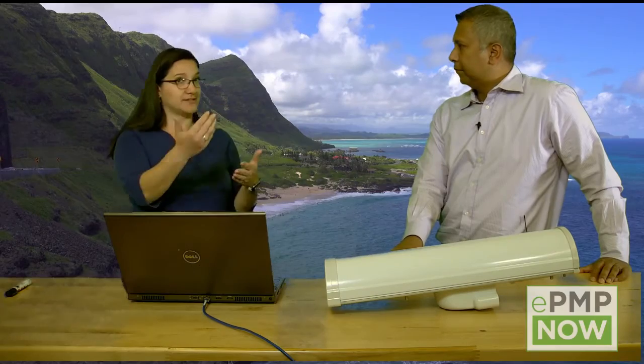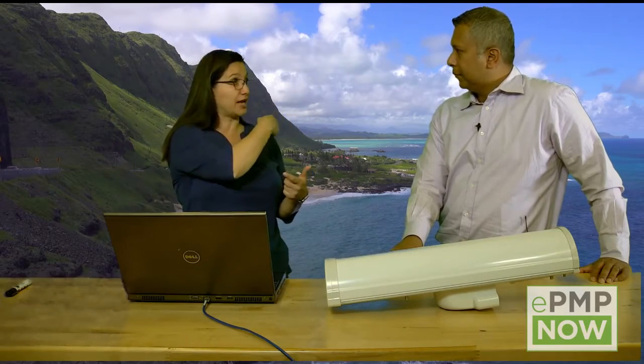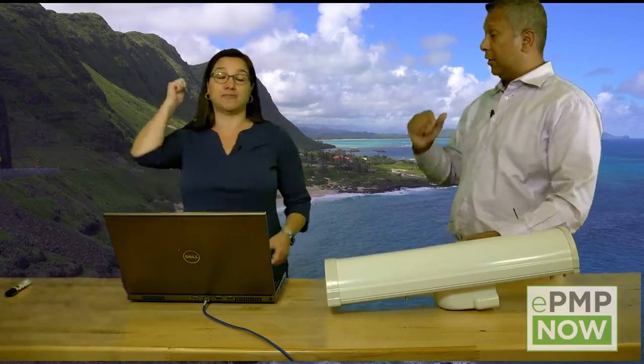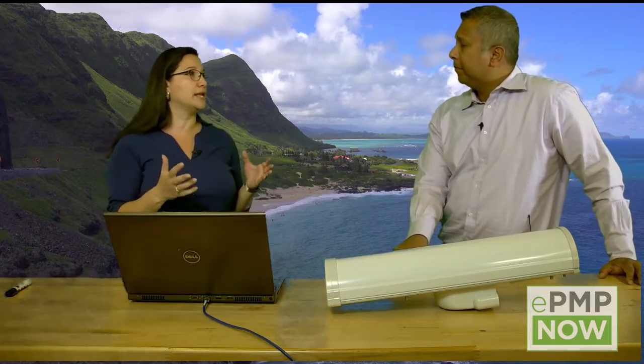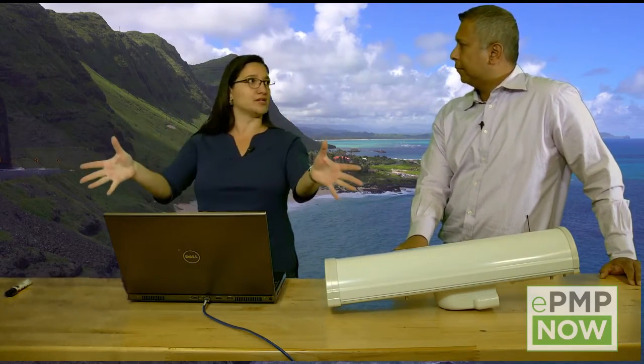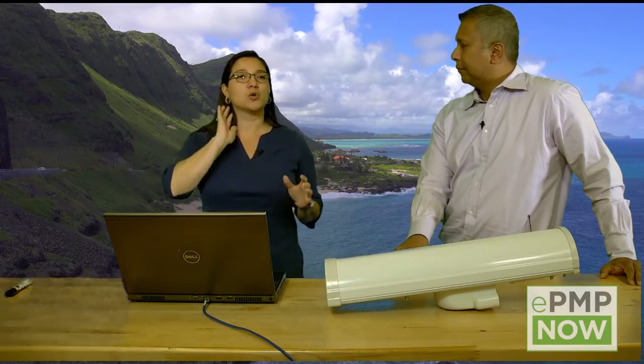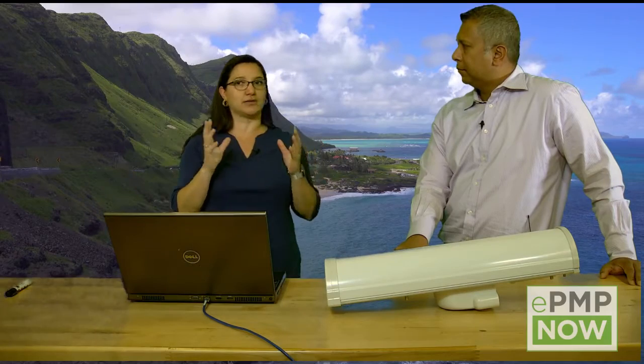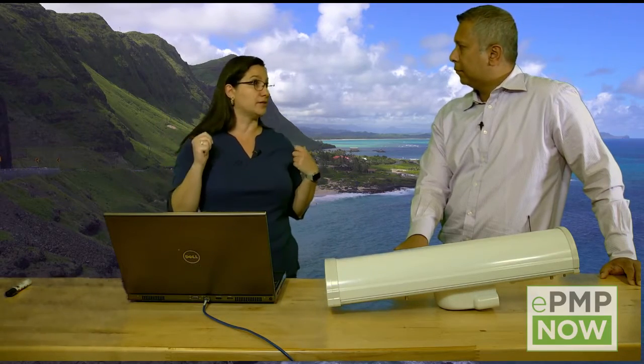have your subscribers. So you were talking about the front to back. The back lobe is 180 degrees in the other direction. I see, so it's behind the antenna, essentially. It's behind me, and I want the energy going in that direction to be as small as possible because my subscribers are all in front of me. So one parameter is the front to back ratio, the ratio between the signal strength in front and the signal strength in the back.